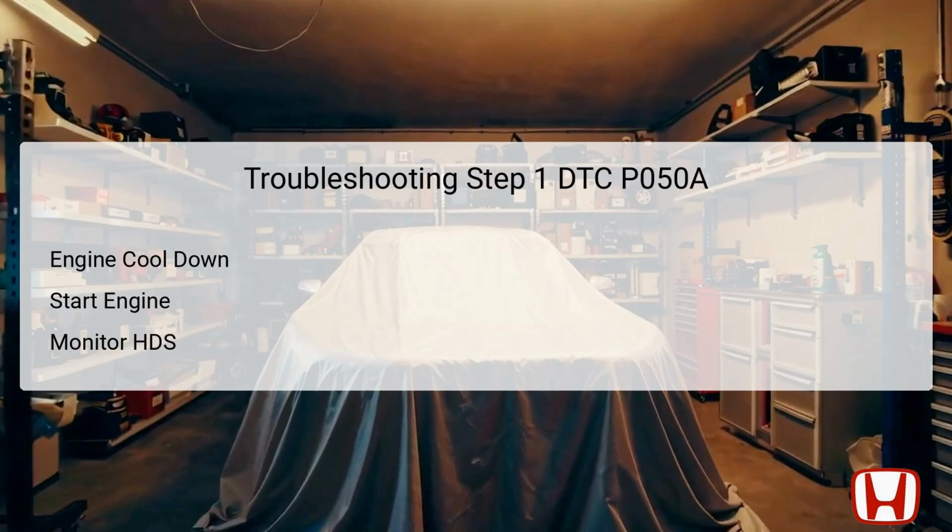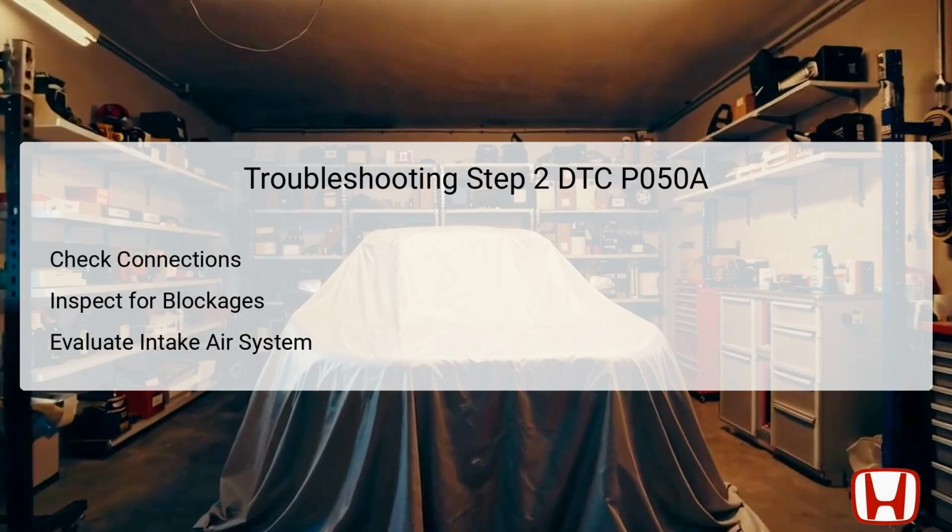Upon confirming that the engine is at an appropriate temperature, start the engine and allow it to idle for over 10 seconds. During this time, monitor the Honda Diagnostic System, HDS, specifically for the OBD, onboard diagnostics, status tied to the PGMFI system. This initial procedure is vital for determining if the DTC persists, signifying a deeper issue within the air management systems.